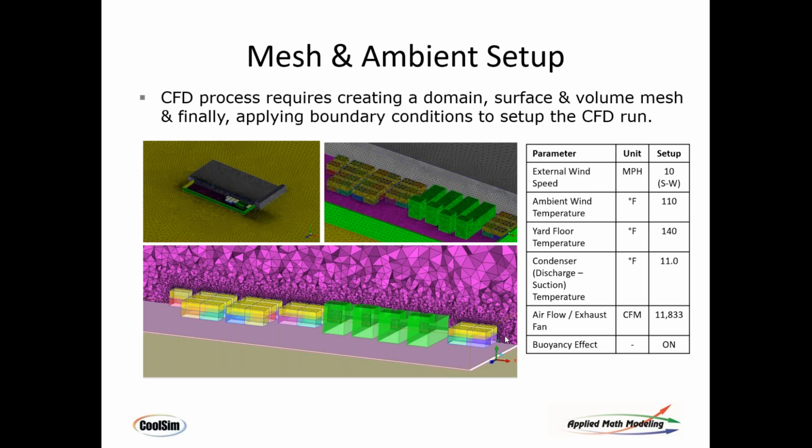Thank you, Paul. So what happens in this mesh is we need to have a denser mesh or more mesh near the exit in the chillers where the air is coming. But very far off from those chillers, we do not need a very big mesh because the gradients of flow or temperature are not very high there. Now, some people also wish to use a very fine mesh, but that would only be causing more computational time and not a very significant increase in accuracy. We used approximately 2 million mesh elements here, and that we found was good enough to simulate what we wanted as a result.